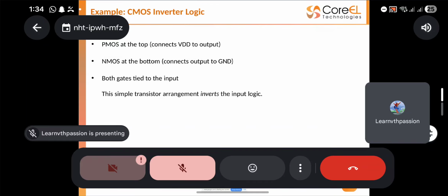Together with that, we have to give the voltage. Voltage can be given using VDC, and we will give the V pulse. VDC mainly will connect to VDD, and V pulse will connect to the input. VDC is not necessary, but if you give it also, it's not an issue. It's based on your circuit design. However you want, you can design. Some will use VDD and VSS instead of ground. Just add the VSS. You can even add ground.